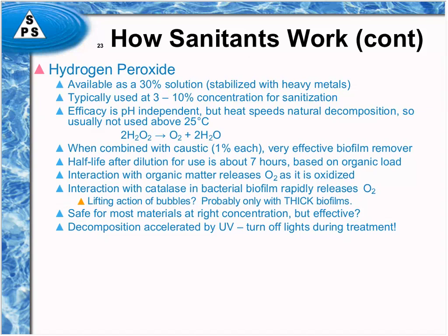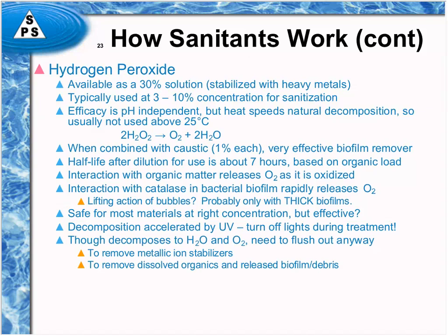Decomposition is accelerated by UV, so make sure you turn any inline UV lights off during this treatment. Even though it's decomposed to oxygen and water molecules, you need to flush it out anyway because it will not completely decompose within your treatment time. And also you need to flush out the metallic ion stabilizers as well as any dissolved organics and whatnot that you've released from that treatment.